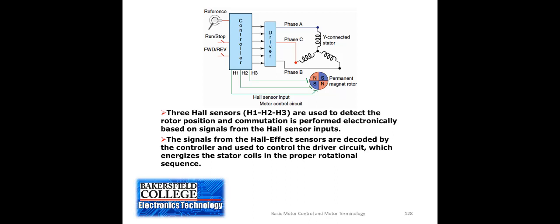So with the motors that we have, these servo motors will not operate without a controller. We cannot connect them directly to three-phase power and have them work like we want them to, because of the way that they're built. However, when we put a servo controller attached to that motor, they have the most precise speed control of all of the motor types that we would normally look at.